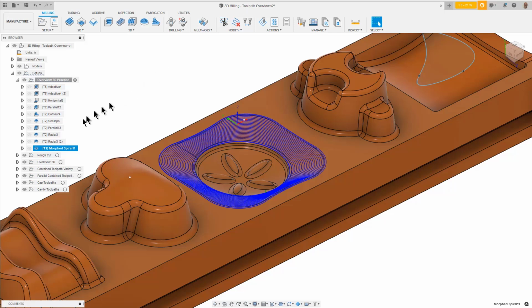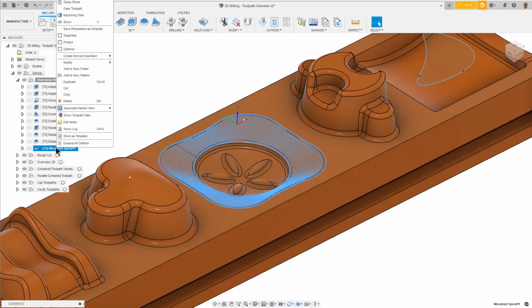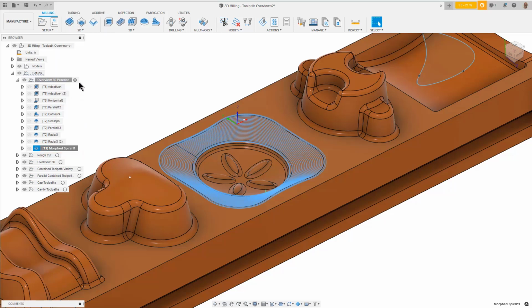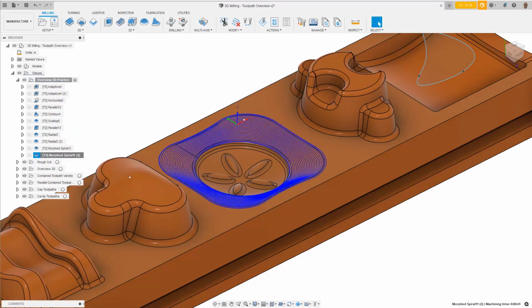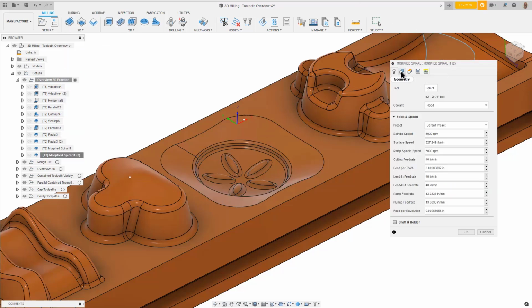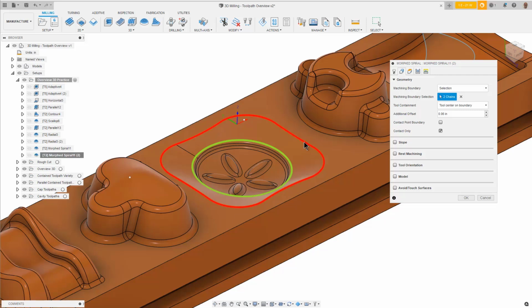Now let's duplicate that toolpath. Right-click over top of the duplicate and select Edit. Go to the Geometry tab. Click on the outer chain and select the garbage can to delete it. So we kept the circle chain. Now select each of the outer ovals. You should now have 6 chains.